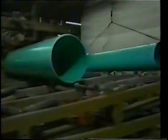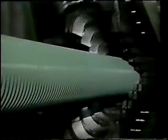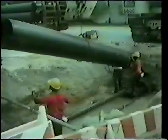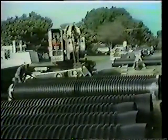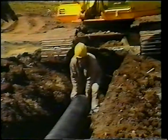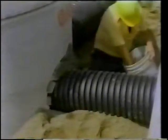Thermoplastic pipe, such as PVC and PE, can be of the solid wall type or structural profile wall, with a smooth interior surface to reduce friction and increase flow. Solid wall pipe are used for pressure applications, while profile wall and corrugated PVC and PE are used for gravity storm sewer and drainage systems. Thermoplastic pipe do not require coatings for corrosion protection.